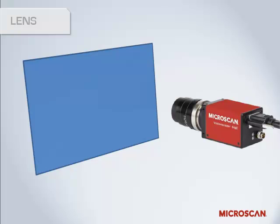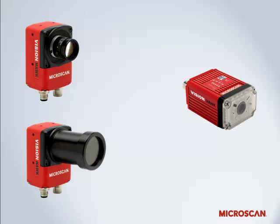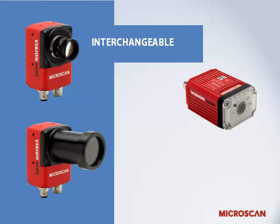The purpose of the lens is to capture the image and deliver it to the sensor. The lens will determine your field of view, depth of focus, and your focal point. Generally, you'll find one of two different lens types in a vision system: an interchangeable lens or a fixed lens. Interchangeable lenses are typically C-mount or CS mount. The right combination of lens and extension tube will acquire the best possible image.